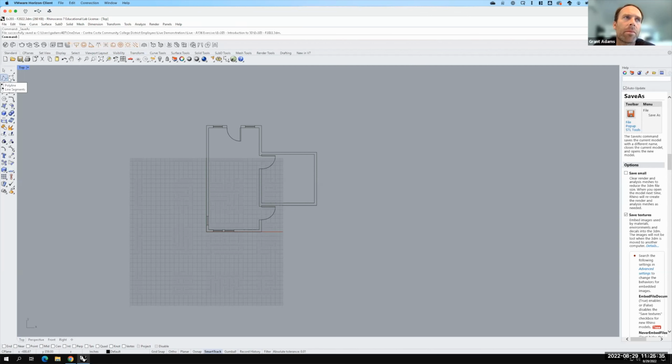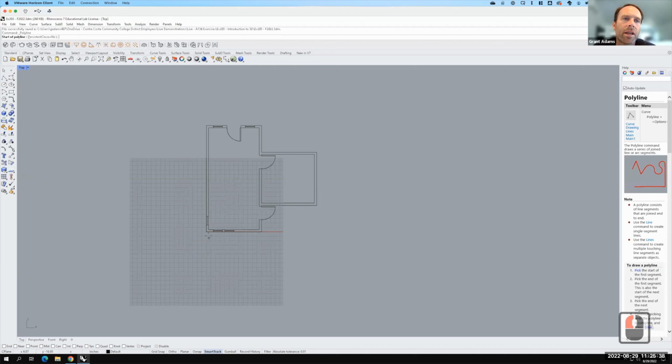So I'm going to go ahead and use my polyline tool right here to give myself a bit of a reference. It looks like I'm not snapping yet, so let's go ahead and turn on my end snap, my mid snap, and my perpendicular snap. Those are the 3 that I tend to leave on. And we'll come down here, an arbitrary amount, it doesn't really matter how far I go, and we'll come across. Now I'm using references here. If I hover over that corner point, you see that the little dot in the corner turns white. When that happens, I can pull straight down and I get that white reference line. And then because I have perpendicular snap turned on, it will stop at a nice perpendicular line right there.